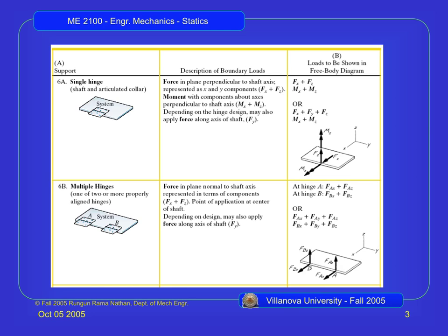So Fx, Fy, and Fz are in the diagram, but M, whatever that direction would be in this case, is not given in the diagram. So no force is prevented, or no force is allowed this way, or this way actually. Okay, it's not allowed in this direction either. It's not actually necessary to even show it in this direction because this is fixed. Let me explain why it's not shown. As soon as you have two other forces there in those two moments, it's actually assumed that it cannot move this way either. So this Fy right here is also really there, but you don't even have to draw it there because of the fact that it's not able to move in those other directions.